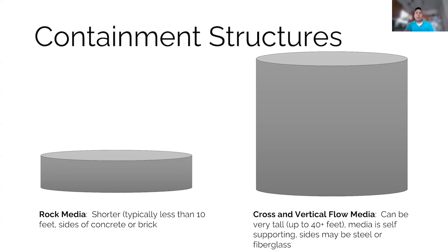They might be made from something like fiberglass or steel and can be up to 40 feet tall, like we mentioned, and where the medium is about 20 feet. But then there will also be ventilation ports around the base to allow airflow. And these types of structures can also have mechanical vents to control the flow and kind of redistribute the pressure in the trickling filter.